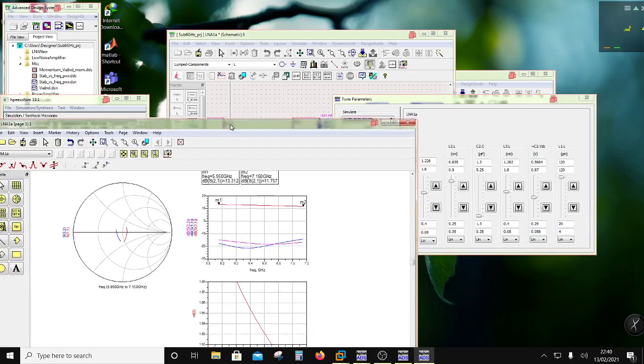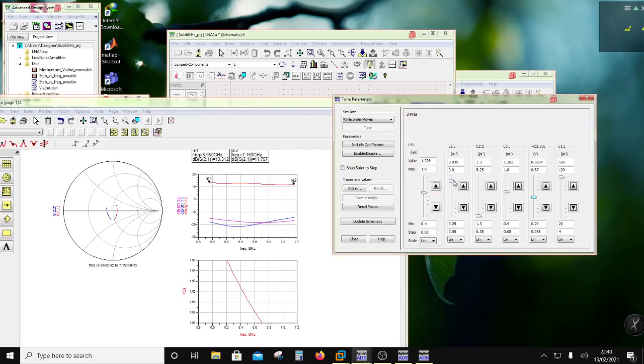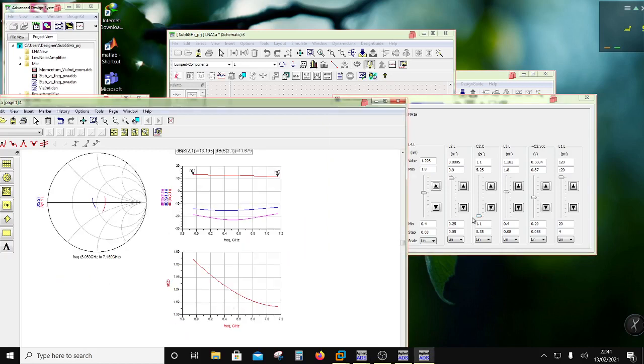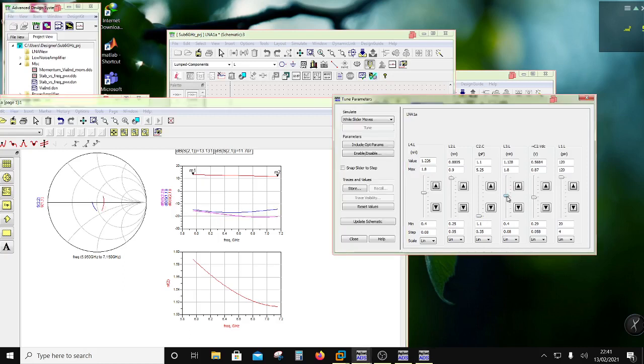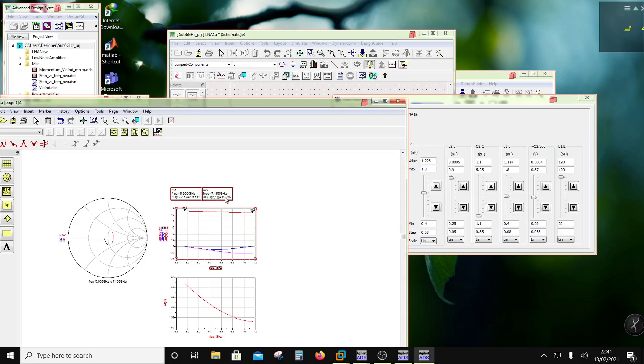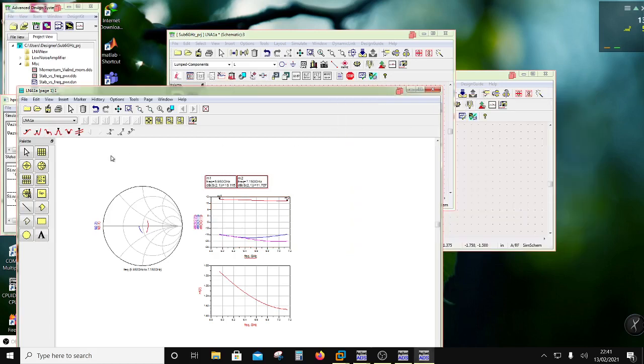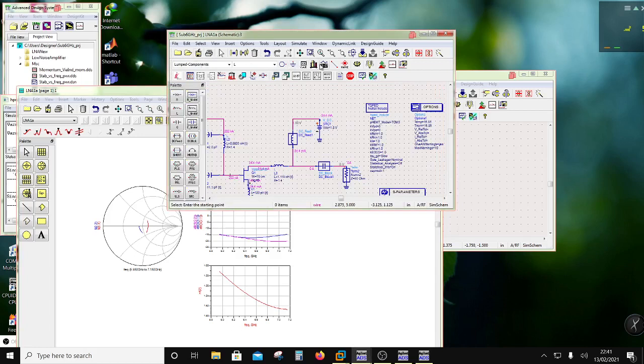How much did I sacrifice on the noise figure? Okay. So really, just 1 second. Okay, let's see. 11 and 13. 11.7 is almost 12. 1.4 dB of variation. Okay, I'm going to accept that and say update and close this and look at the current, because current I want to not exceed 20.